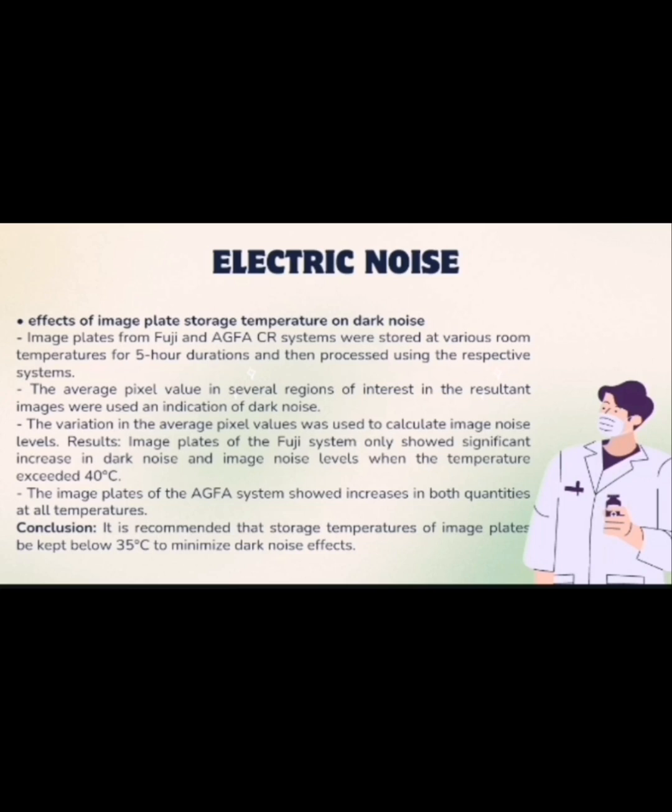Higher temperatures generally increase dark noise due to increased thermal energy, leading to more random electron-hole pairs being generated within the material. This can degrade image quality and reduce sensitivity. Storing image plates at cooler temperatures can help minimize dark noise and preserve image quality over time. The average pixel value in several regions of interest in the resultant images was used as an indication of dark noise. The variation in the average pixel values was used to calculate image noise levels.